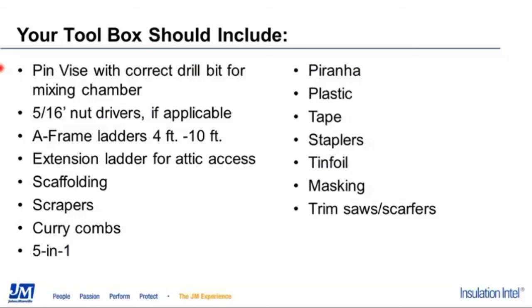Having plenty of plastic, tape, staplers. If you have never used tinfoil for masking, we've all had jobs where, quite frankly, the masking takes longer than the spray job. Tinfoil works out really well. If you've got garage running rails, you can pull out a 10-foot long strip of tinfoil, lay it over the top, crunch it, and you're done, and you're moving on.